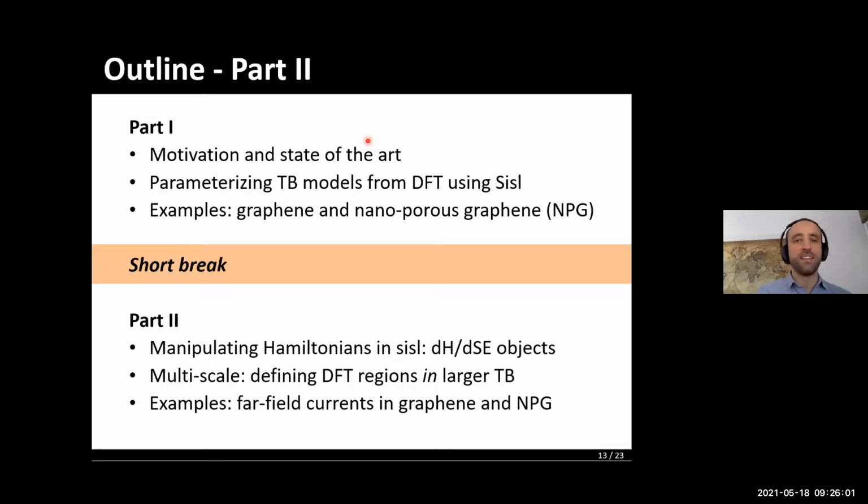Indeed, you can just check out the section on electrostatic gating in the SIESTA users guide to understand how to do that. There are different ways of doing that. You can either apply a charge on a plane at a certain distance from your system, and that would induce a charge on your system. This is for the case of 2D materials, for example.